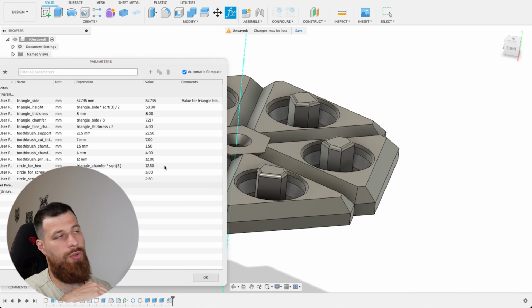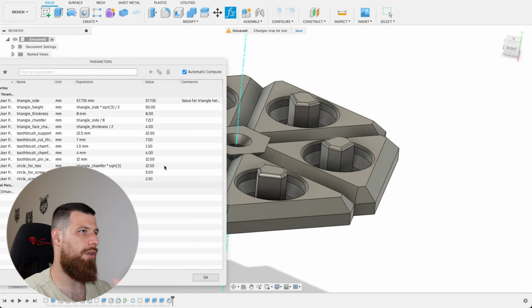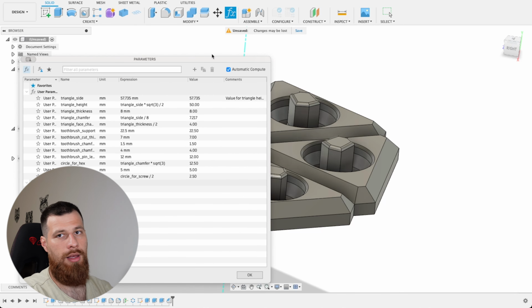But there's one more thing I would like to show you, which is actually how to include tolerances directly into this design. So tolerances are quite important for your projects, especially when it comes to 3D printing. Having a parameter that defines your tolerance level for each connection between parts is very important, as you might collaborate with friends, with colleagues, with other fellows from the 3D printing community, and you want their prints to look quite good. And if you ever share your Fusion360 parametric file, then they should be able to update the tolerance that you set so that it will work properly on their machines as well. So let's do exactly that.